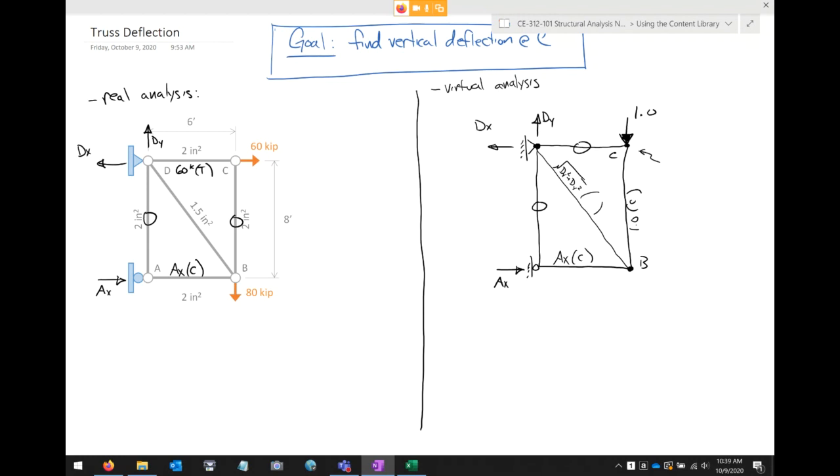Tension, exactly right. Because if you look at joint D, here's joint D. There's a member, and a member, and these are zero force, and you're going to have action there and a reaction there. That's got to yank away. It's got to be in tension. So actually pretty slick. It needs to point in the opposite direction of the two reactions. Exactly right. Okay. Let's stop.